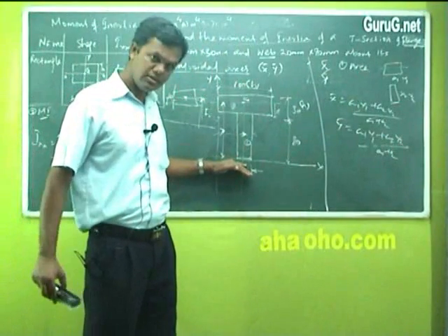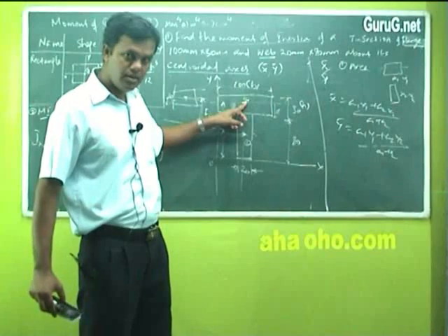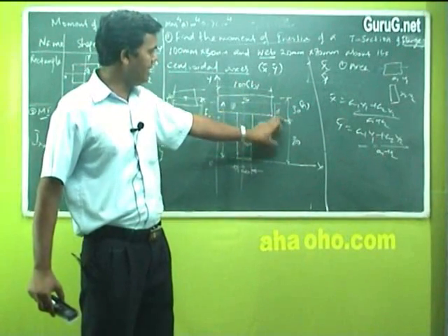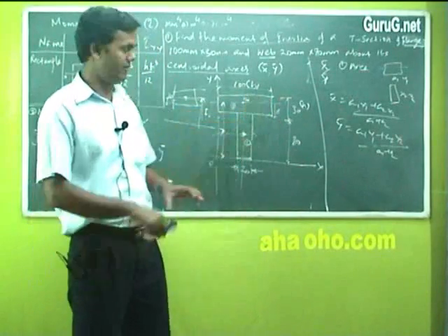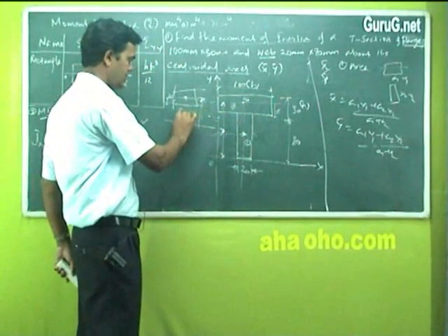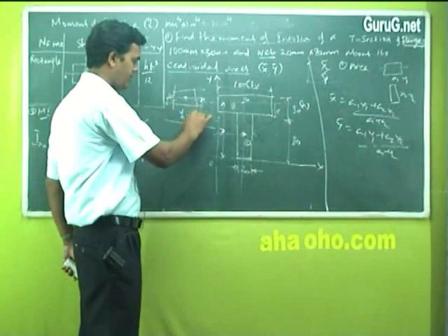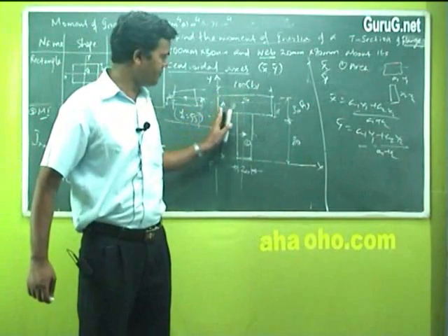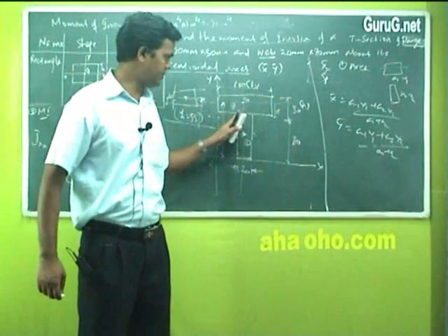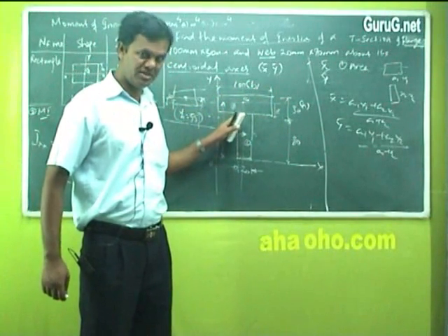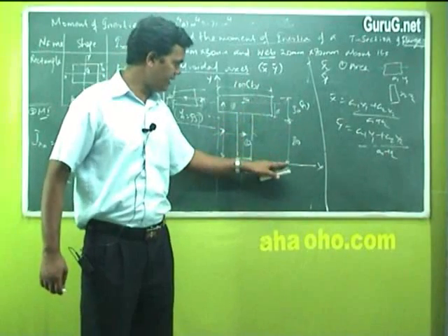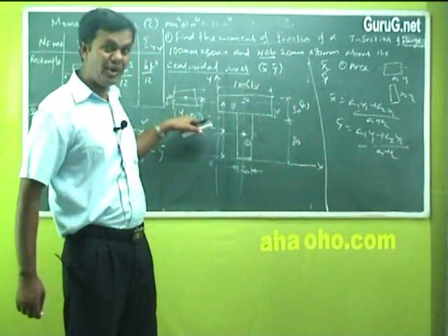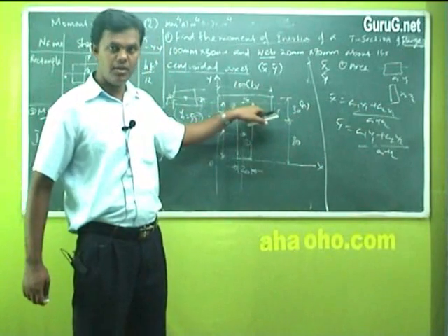From the base, for sketch number 1, you travel a distance of 80 plus 15. Y1 is 95. So this is not h bar. From the base, the center of portion number 1 is at a distance of 80 plus 15, which becomes 95. This is the Y1 value for sketch number 1.